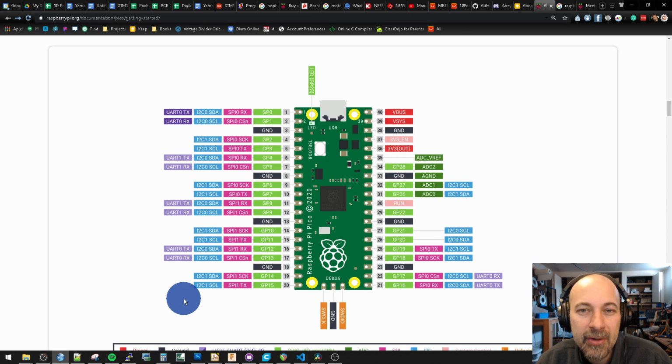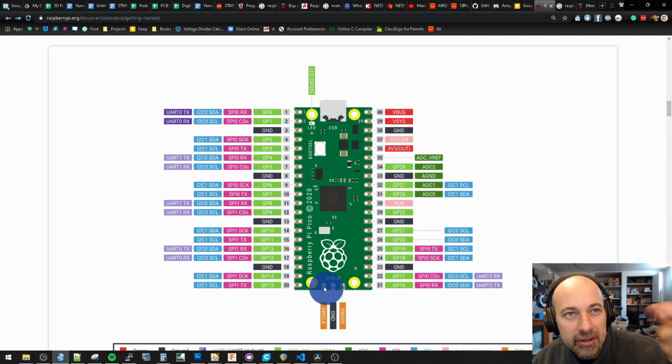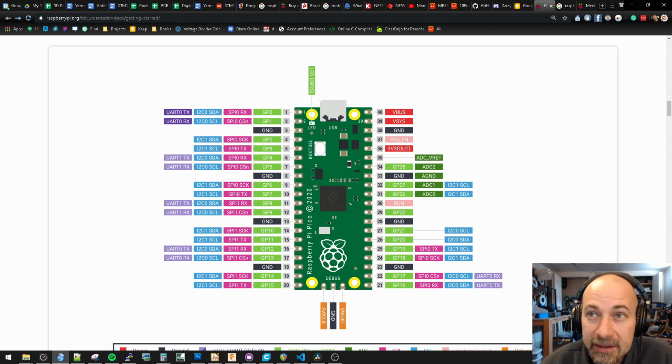You can do that in the STM32 Cube IDE, for example. But I don't know if in Arduino you may not. So I'm not really sure how we configure this, but it's like this with lots of things. Lots of things have redundant pins so that you can pick one or the other. And this is very helpful for layout. If you want to keep all your layout on a 2-layer board and you don't want to tear up the ground plane on the bottom, then you can adjust your pins around so that the tracks don't overlap. This is big. It's a big deal. And it could be the difference between using a 2-layer board and a 4-layer board. You're looking at real cash then. So that's cool. Again, somebody put some real thought into this. I'm really excited about that.